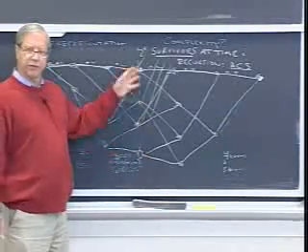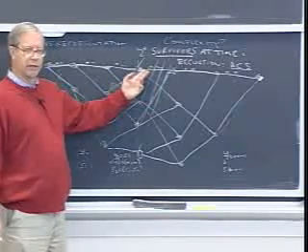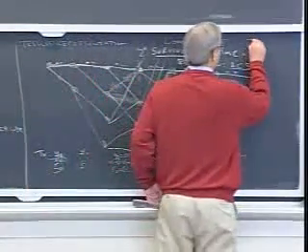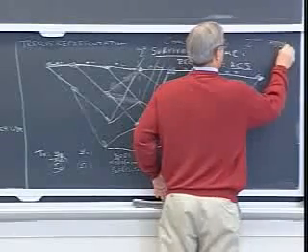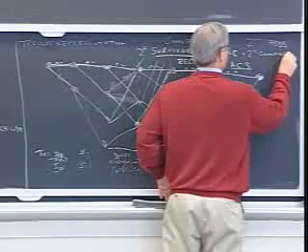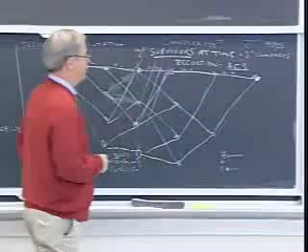Is that clear? We have 2 to the nu states, 2 branches out of, 2 branches into each state, always for rate 1/2. So we have 2 to the nu plus 1 additions. We get 2 to the nu compares, 1 for each state, and you can consider the select to be part of the compare.